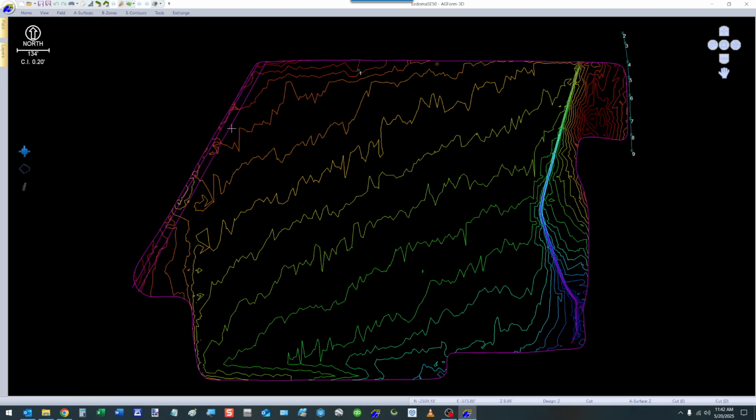Here we have break lines, which you can use for two reasons. One, a break line if you're doing like a ditch and you want all the triangulation to follow that line and not skip across the ditch. Then also, these are two pipelines going across here that I marked. I wanted the elevations to be used, but I also wanted to differentiate them from just normal interior points, so I used it to identify those sometimes. Over here, we have a landmark line, landmark points and a line. You can connect these together, and that's part of something you would do in your survey system.